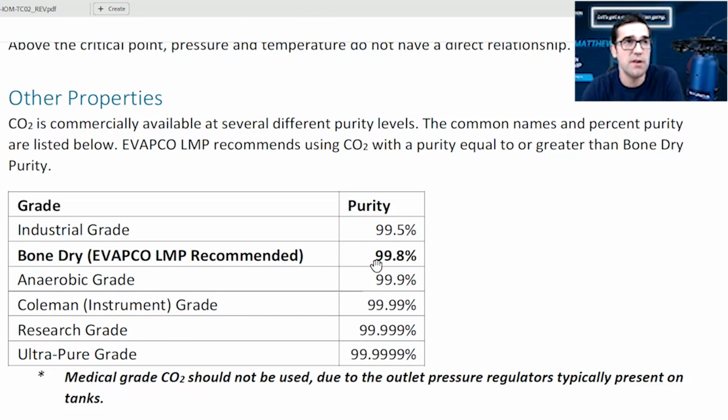And I've seen other ones where they say, well, you can't use Dewar tanks. And what Dewar tanks are, these are larger tanks. They have like a refrigerant circle on them and they're a lower pressure. So you get like 300 or 400 psi, less than 30 bar, I would say, 20 to 30 bar inside them. So this pressure is not very high in there. But if you're in a situation and you need refrigerant, there's no reason not to get that to get your customer up and running.